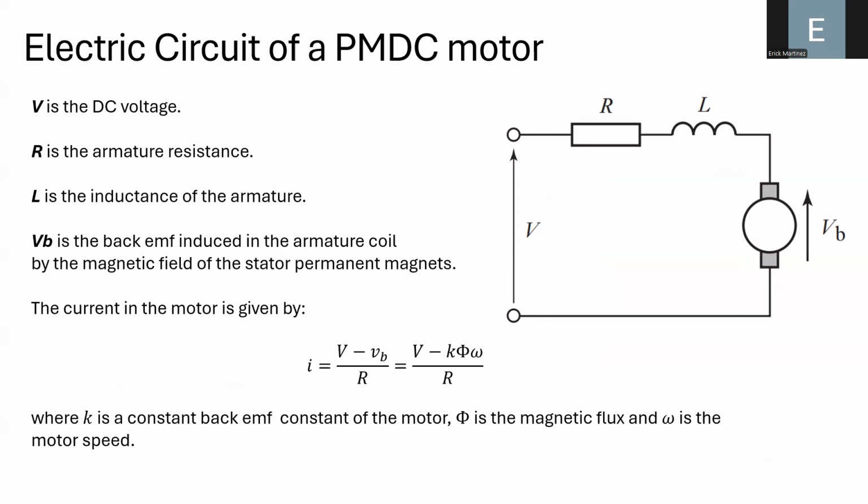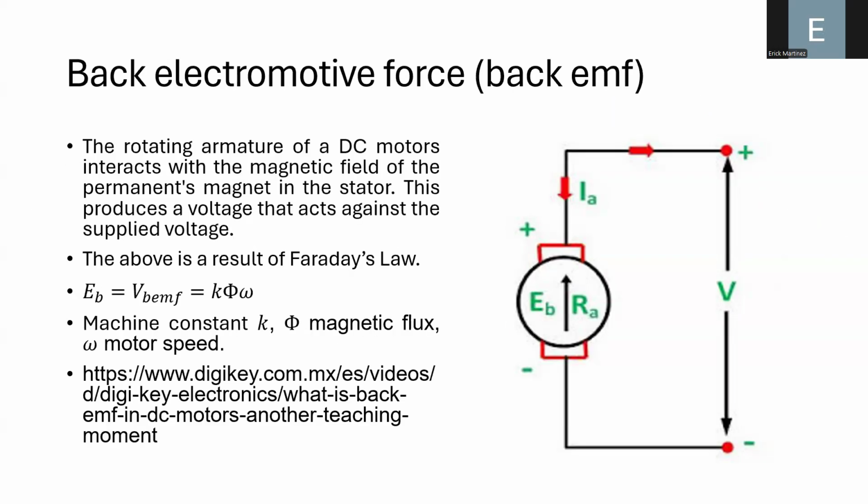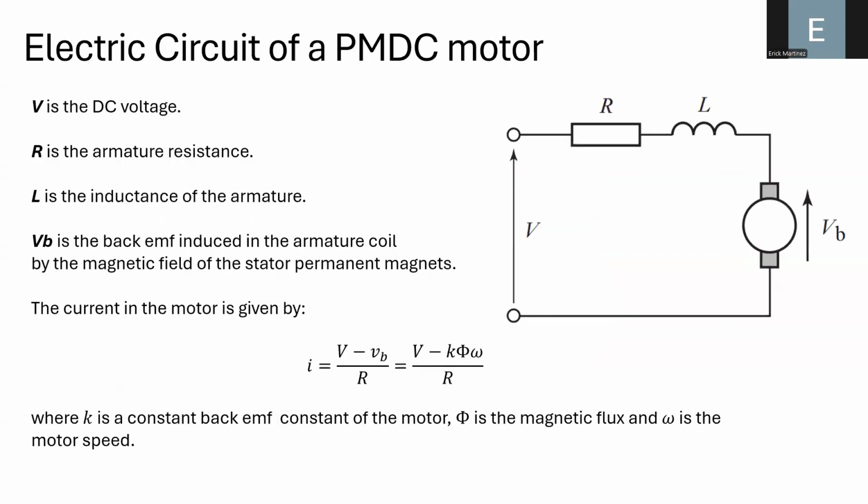Remember that from the AC circuit class, we discussed that these elements have a resistance that depends on frequency. But here you can observe that we are getting rid of that because of the impedance of an inductor in DC, where we don't have a frequency. In DC, we can say that omega is equal to 0. So the impedance of this element can be discarded, and we can represent the presence of this inductor with a cable.